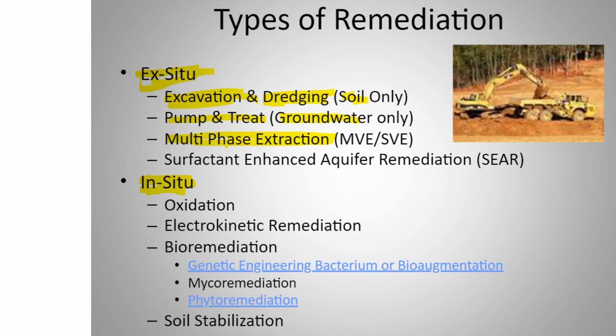Again, in case of contaminated aquifers, you can enhance the production of surfactants, or provide surfactants, make amendments in a treatment plant, and remediate it. You can also add oxidizing agents, or treat it with electrokinetic radiations, or use stabilizing chemical agents to stabilize the soil so that the soil does not denature any further. So you have these various physical chemical techniques, and bioremediation is just one of them.